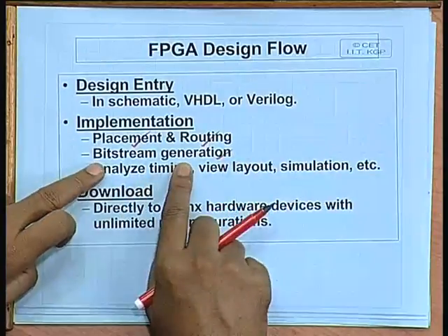Bitstream generation is required in terms of the programmability. Whatever placement and routing you do, ultimately in a programmable FPGA, it will boil down to the bit patterns that will be required for the corresponding programming. So, ultimately you will have to generate a long bit stream which will be downloaded onto the chip and which will be programming it according to your need.